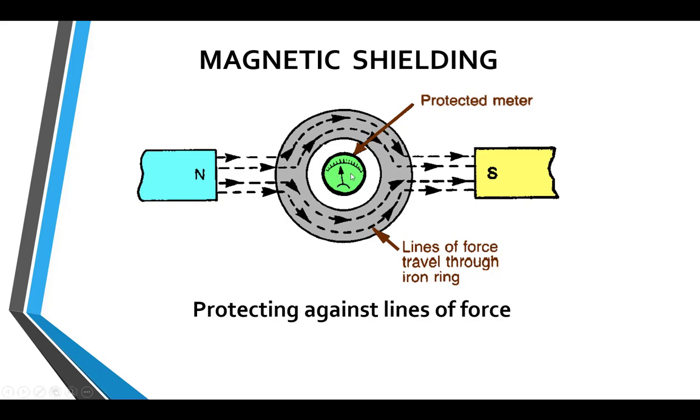the wires and conductors in this meter, that can cause noise, cause interference, cause the signal to be inaccurate. It can cause the induced voltage to mix with the voltage from the measuring device that this thing's looking at and give you faulty readings. So here I can't use paper, as we saw before. It doesn't provide shielding, so I'm using metal.